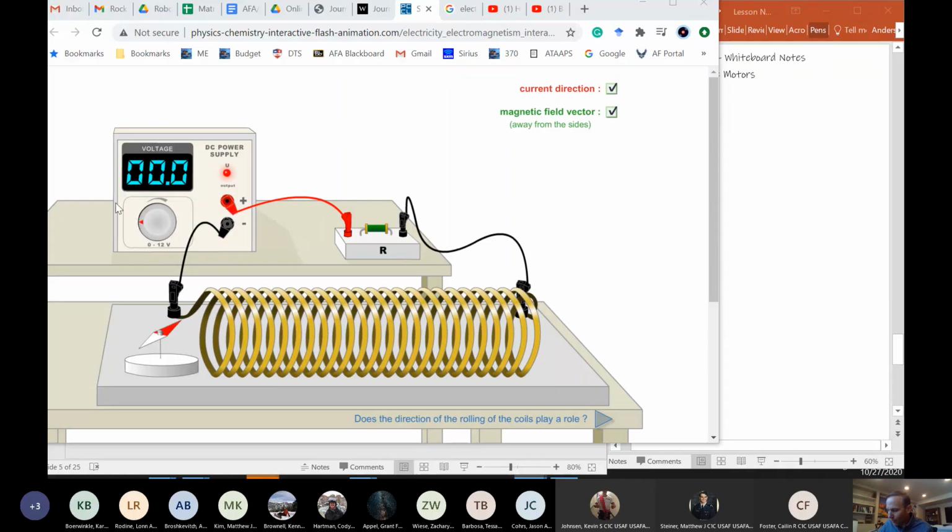So here, if I turn on the current, we can use the right-hand rule: wrap your fingers in the direction of the coil wires, in the direction of positive current flow, and your thumb will tell you the direction of the magnetic field that is generated. In this illustration, if I wrap my fingers around those coils of wire, the magnetic field should go to the left.